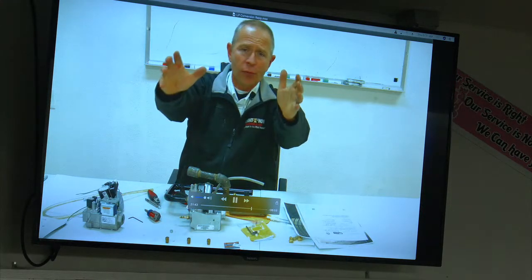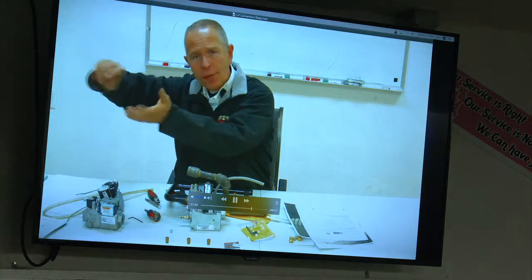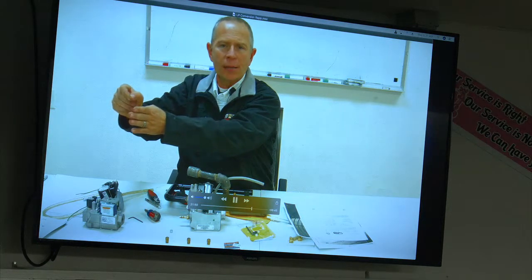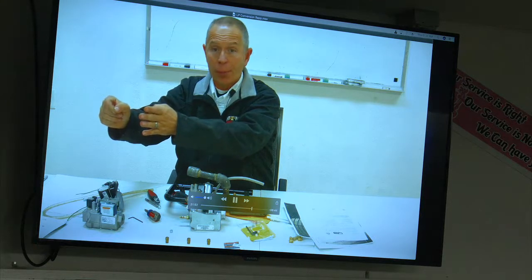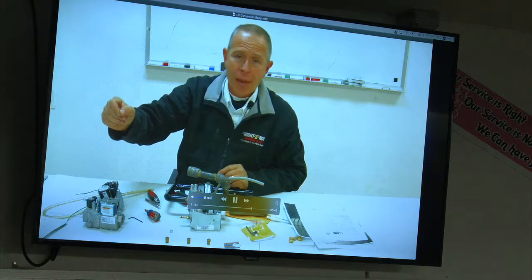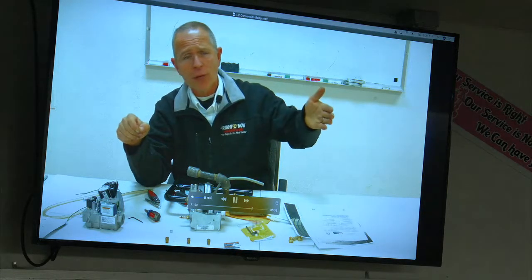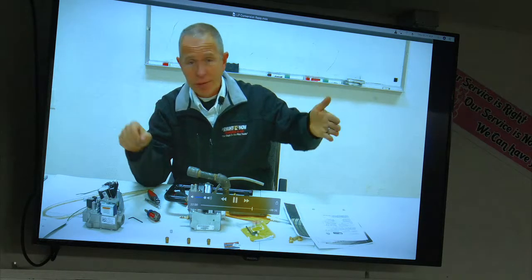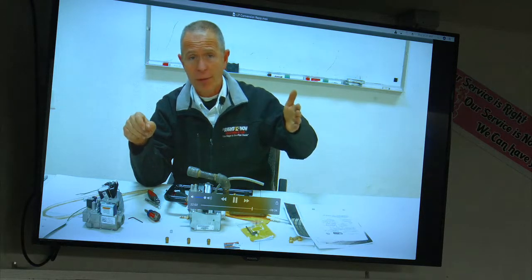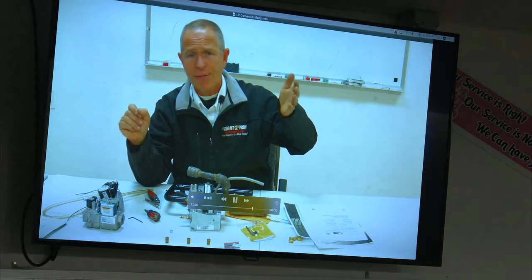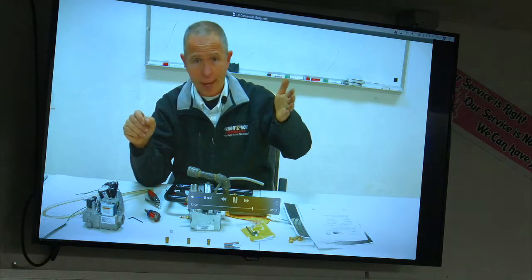So picture a duct run, and where it turns, as soon as it turns, that is going to get you out of the radiant of that, and that is the proper place to take the measurements for your temperature rise. So if we have 70-degree return air, most of these units, there are ones that are different, but most are going to be 30 to 60 or 30 to 55 or 40 or somewhere in that neighborhood.